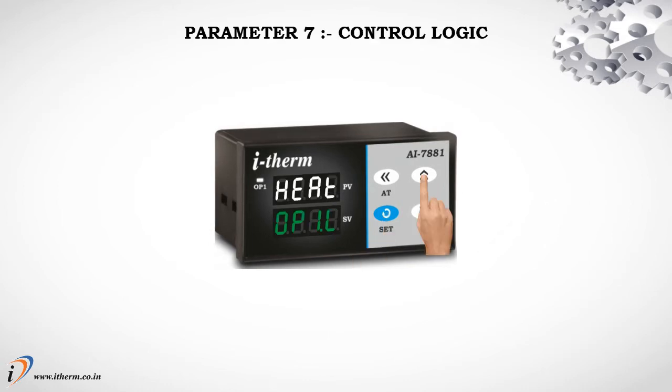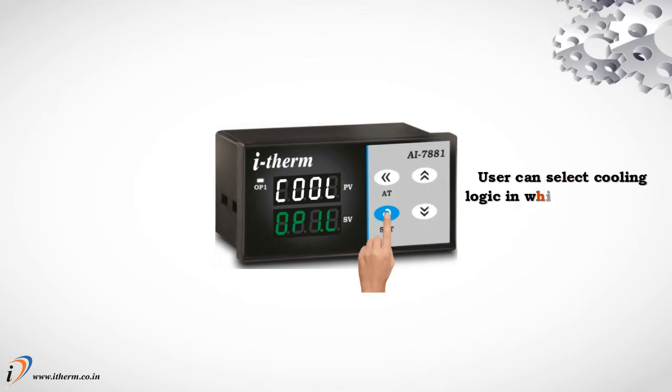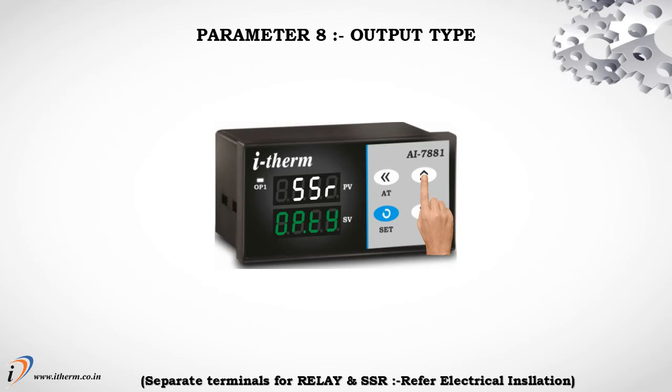Parameter 7, Control logic. The user can select heating logic, in which output 1 will remain on until the process value is less than the set point. The user can select cooling logic, in which output 1 will remain on till the process value is more than the set point. Parameter 8, Output type.